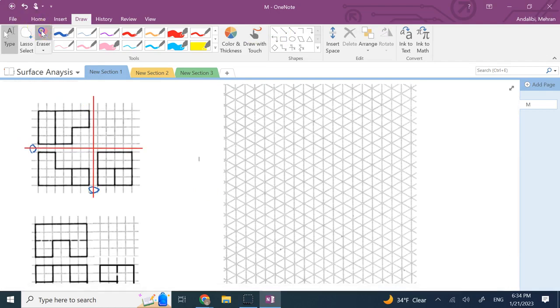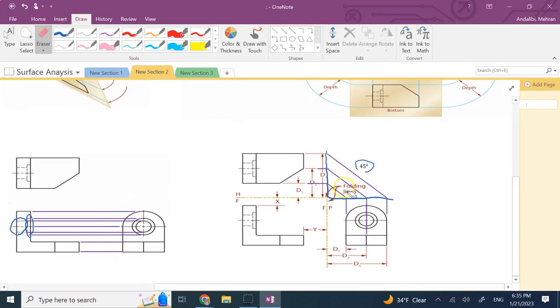Okay, and those would help me transfer the dimensions between right and the top view, as you can see here. So let me tell you an example about that here. So if here I say this surface is A and this guy is B, what are they represented by in this top view? So if I use this vertical 45-degree and horizontal lines, then I see that A represents this guy and B represents that guy, that vertical edge, right?